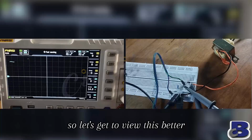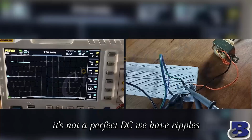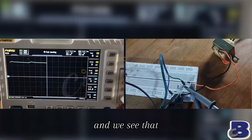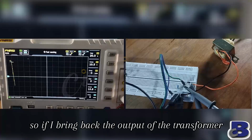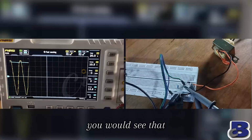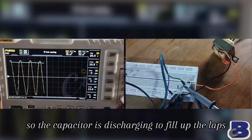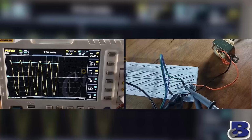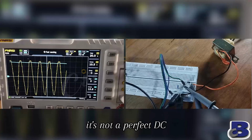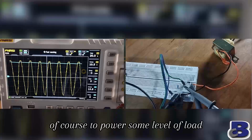So let's get to view this better. So we can see that we have ripples. Okay. It's not a perfect DC, we have ripples, and we see that those ripples come from the crest of the wave. So if I bring back the output of the transformer, you would see that those ripples come from the crest of the wave. So the capacitor is discharging to fill up the lapse for when the current begins its fall. It's not a perfect DC, but it's good enough, of course, to power some level of load.